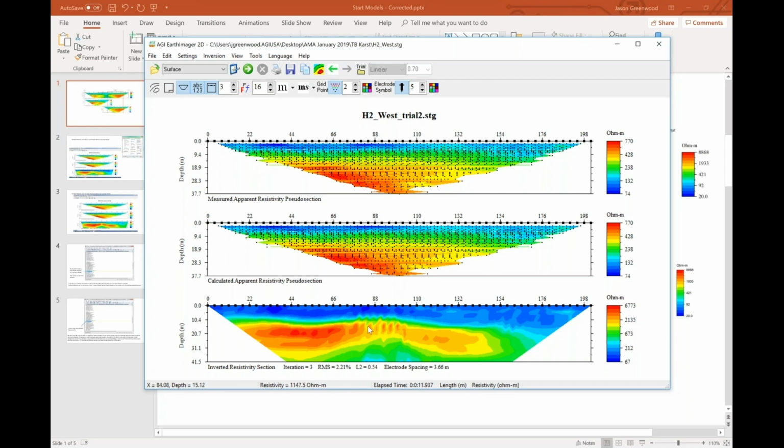So because it's ill-fitting from the start, you end up with these high, low, high. This is typical of instability. It's basically instability in the convergence, and it still has a low RMS. And the depth to bedrock is approximately the same. It doesn't impact the project, I would say, but that joint which is there in the apparent resistivity starting model, final model, is obscured by this.